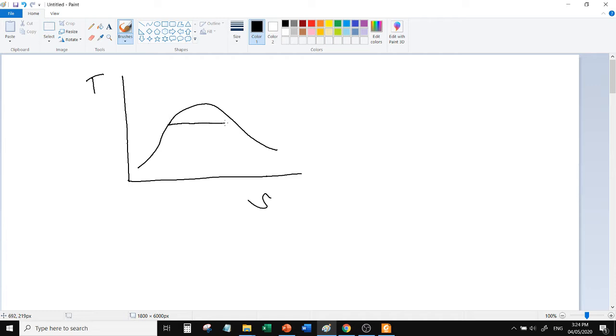So let's draw it, with a bit of slanting to the right, slanting to the right because we have a straight line. And then, no subcooling. So we only work along here, since there's no subcooling. Let's label this as points 1, 2, 3, and then 4.